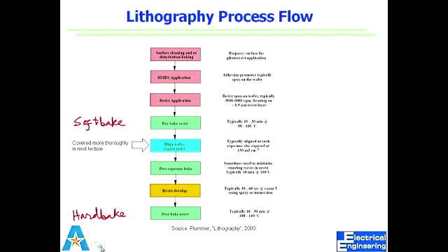So again, now a little more specific on the processing. So we clean the wafer, we do dehydration bake, right? We do soft bake, right? Apply HMDS, spin it, or there's a couple of ways how we apply HMDS. I think I have a slide on that. But we apply HMDS and then we spin the resist, typically from 3,000 to 6,000 RPM, and for 30 to 40 seconds.